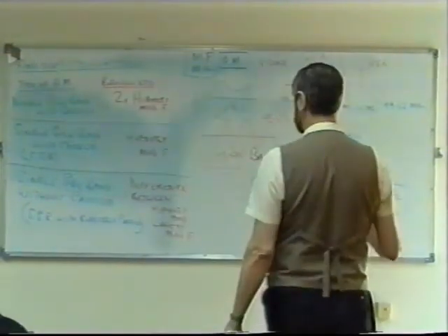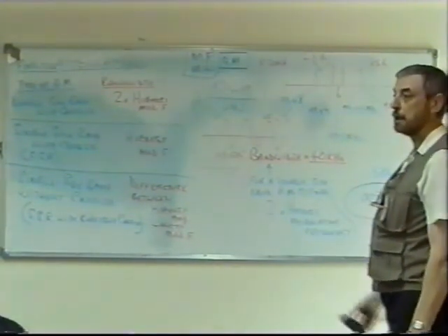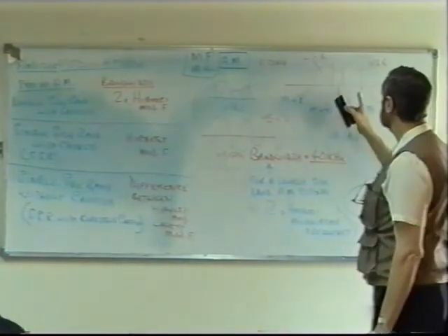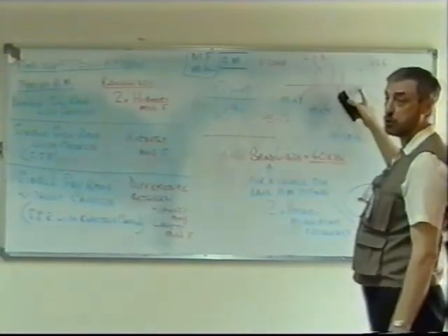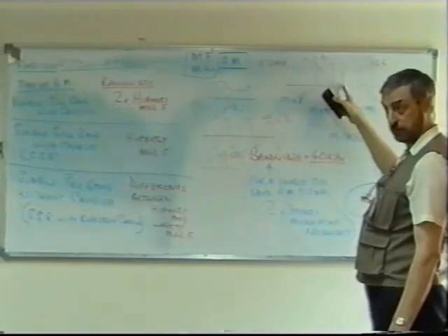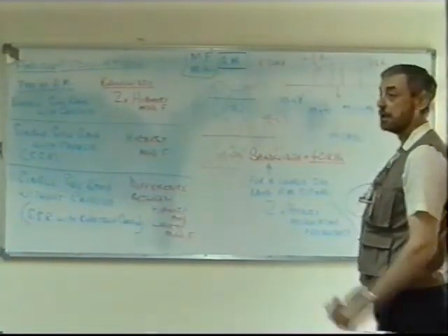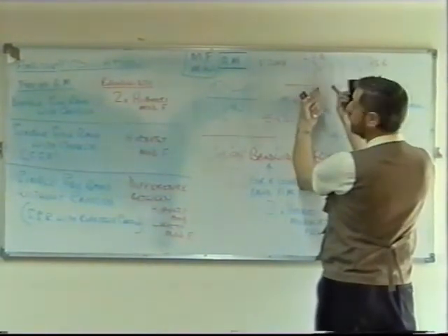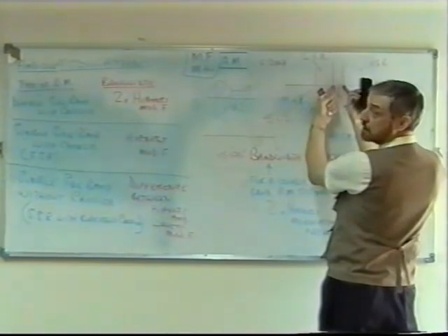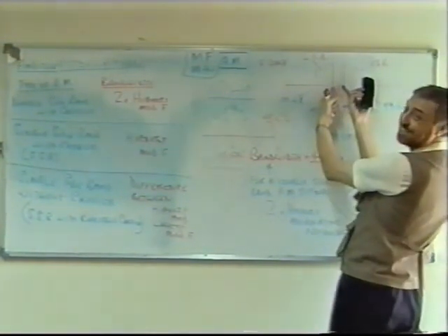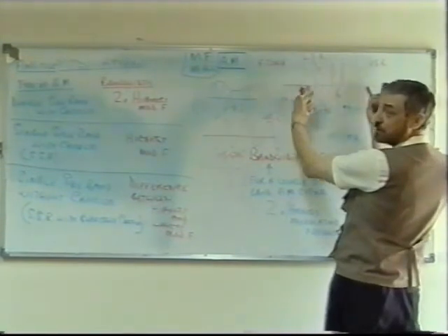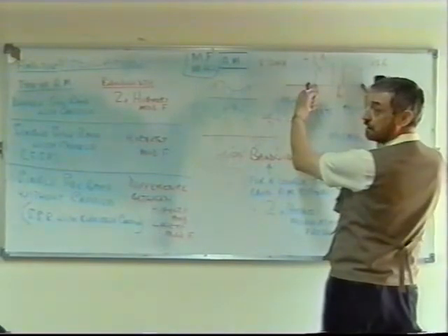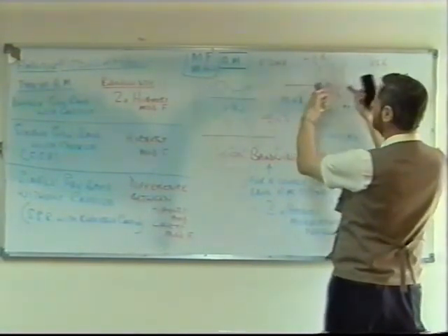So here you see a single sideband without carrier. The definition is between highest and lowest. In other words, if the highest is 20 and the lowest is 5, the difference is 15 kilohertz. So we've got 15 kilohertz here, 15 kilohertz here, but we've also got a little gap here of 10 kilohertz, the difference between the two low frequencies. So that gives me the total of 40 kilohertz. 40 from here to here, 15 from here to here, 15 from here to here.